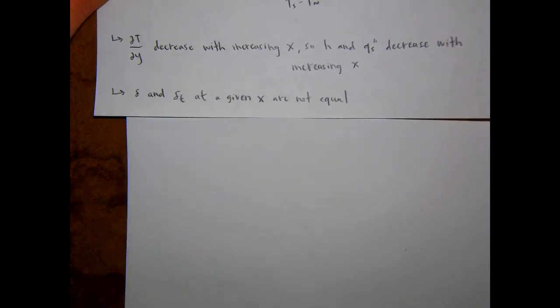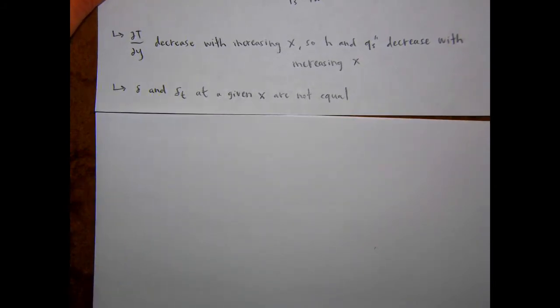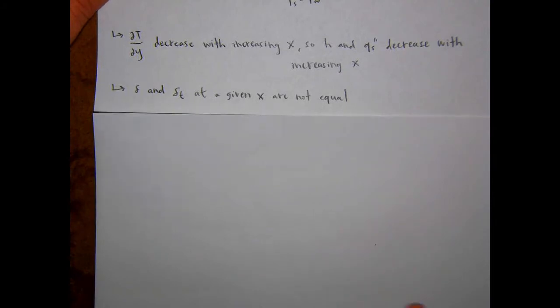So we kind of just showed that one of the implicit assumptions that we've been making up to this point is actually not really true. When we've been doing convection calculations, you've just been given an h value, right? And you're just assuming that that h value applies to the entire surface, that it's uniform over the entire surface, which we've stated as an assumption a couple times. You know, assume that h is uniform, like over the length of a fin or whatever.